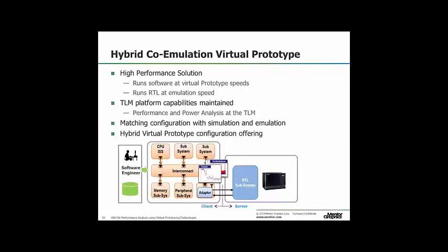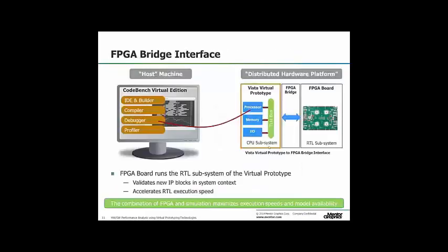So whether it's a pure TLM-based platform or whether it's a hybrid, it's transparent to the software development teams where the actual devices are implemented, whether it's ending up on an emulation box or modeled within TLM SystemC. That becomes transparent. And likewise, we have technology to bridge the TLM world to an FPGA board.